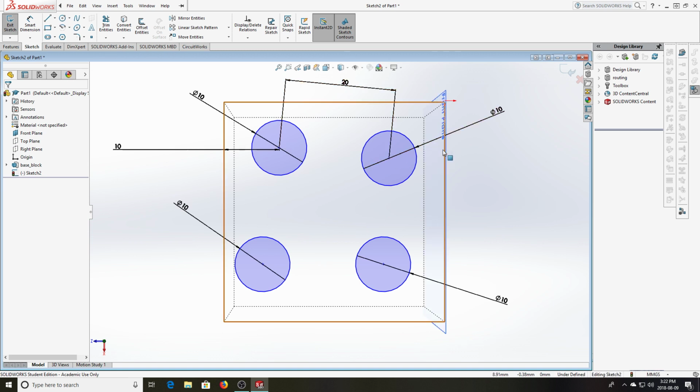So I really screwed things up by over-dimensioning these distances. But this gets into some of the fundamental problems or challenges you'll have with any CAD package, which is it's just solving geometry and you're defining the geometry. Sometimes you define geometry that isn't possible.